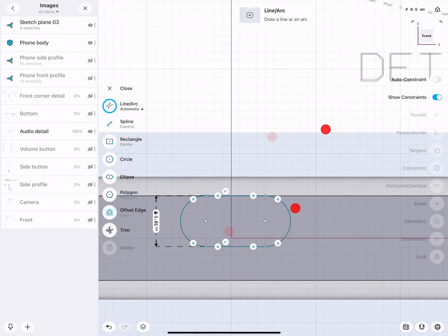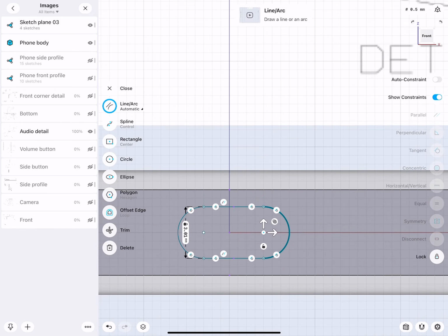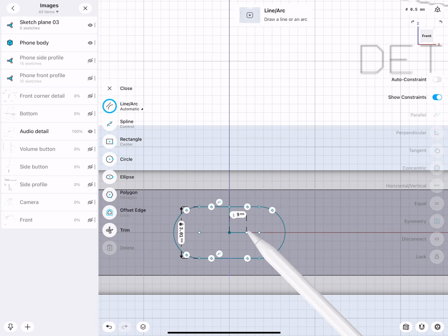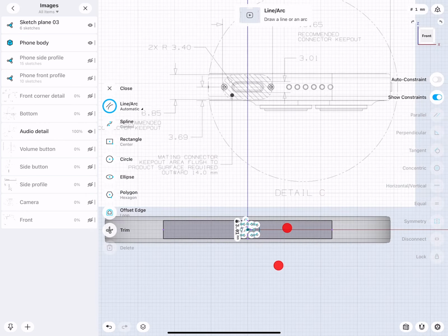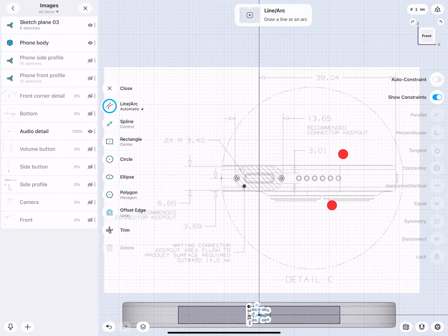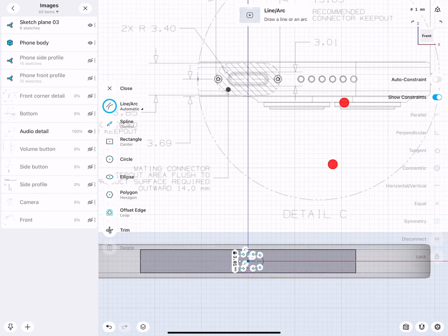Yep. Now you see this jumped up a little bit, so let's move this down to line this up more correctly. At this point I lock, and then this I will make vertical. You see this pulled the whole piece nicely centered. This here I can connect and make horizontal, and then this pulls that point down because the whole construction here is horizontal and tangent. This point is horizontal with that point already, and we don't really know how wide this is.